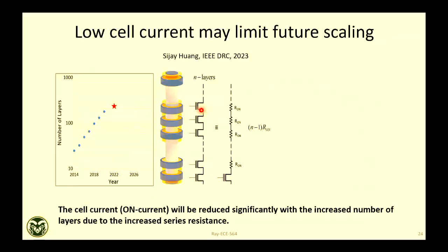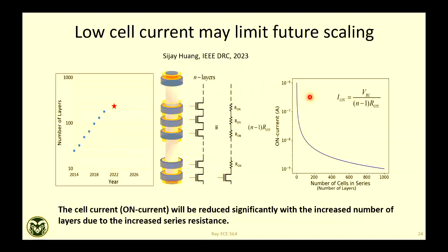So this is one of the papers showing that as the number of layers grows, this lowering in current will take place, because the on current is bit line voltage divided by total resistance. Now resistance will increase with the number of layers because of those interlayer regions. With interlayer resistivity, you cannot control much. Okay, so that's another limitation of having undoped source and drain.